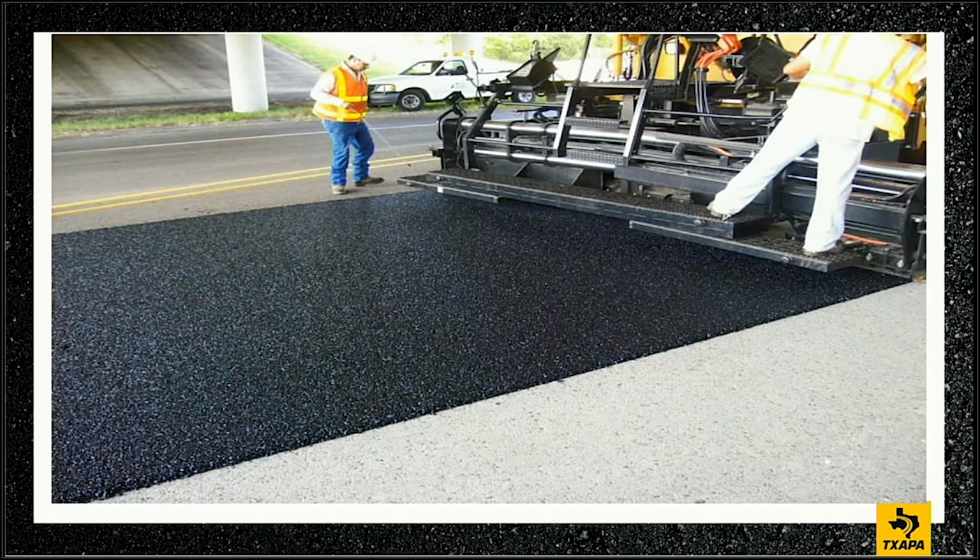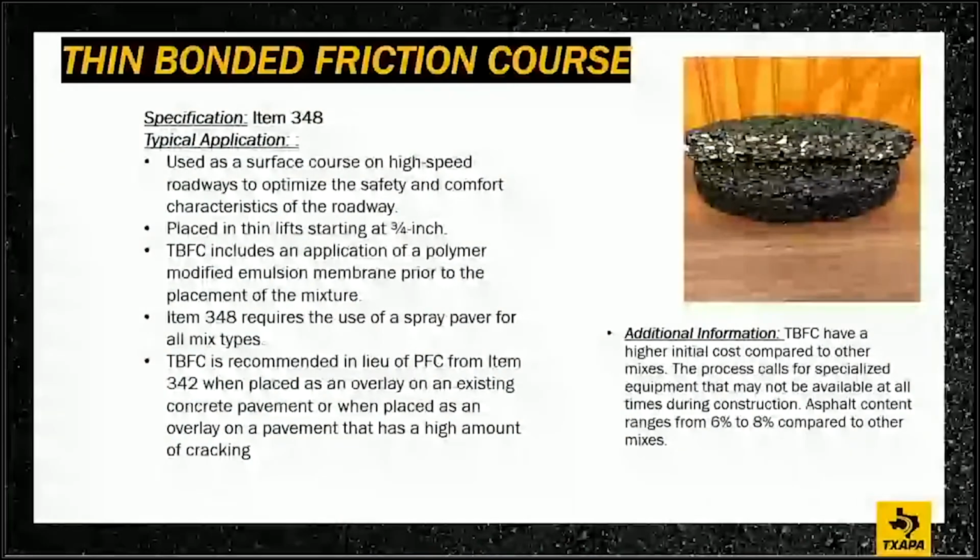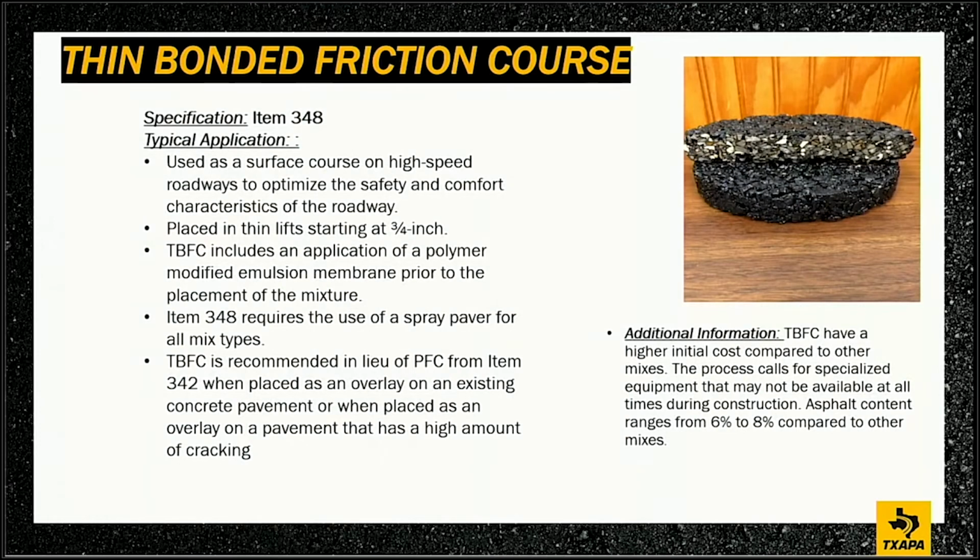You're not measuring density on this material. No, you bring up a good point. What do we measure? We're measuring water flow. So we want to make sure that we get it somewhat seated to where it's going to stay there. And what we do is the permeability test, the reverse permeability test that you do on a PFC. Right. So, by the way, you teach that in your inspector training course? We tell them to run it.